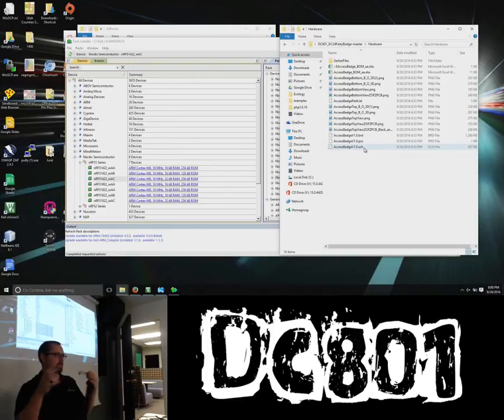So that's where your H file correlates. When I made the H file for our board, I looked at the schematic and verified that these pins were running these LEDs. So when we programmed it, what we did in the program actually showed right on our badge. All the lights that lit up were right. You get the right sequences. Cool. So it goes through that.